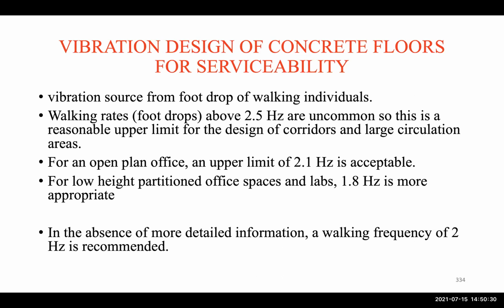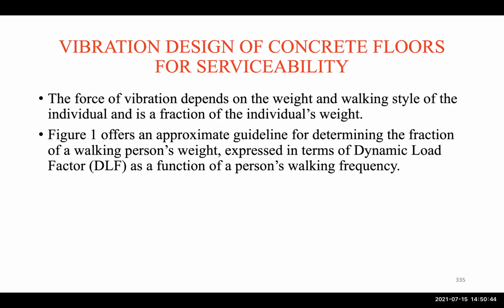So that's why we can use that as an upper limit. For low height partitioned office floors, we can use 1.8 hertz because we have full partitions in an office like that. In the absence of more detailed information, we can use 2 hertz. Okay, so the force of vibration depends on the weight and the walking style of the individual, and is a fraction of the individual's weight.